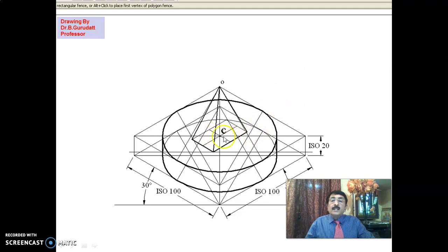Now the problem is you have to concentrate on the visibility. When two solids are placed one above the other, the top solid, as you know, is a rectangular pyramid, and the bottom solid is a cylinder. Now the visibility is, since the pyramid is there, the top surface cannot be seen because it's a point. Left surface and right surface, immediately darken it. Darken the left surface, darken the right surface, back surface and all that, make it light.